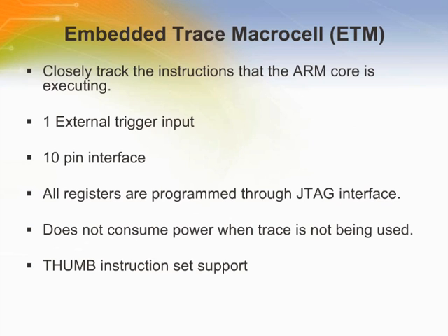As the microcontroller has significant amounts of on-chip memories, it is not possible to determine how the processor core is operating simply by observing the external pins. The Embedded Trace Macrocell, or ETM, provides real-time trace capability for deeply embedded processor cores. It outputs information about processor execution to a trace port. A software debugger allows configuration of the ETM using a JTAG interface and displays the trace information that has been captured in a format that a user can easily understand.